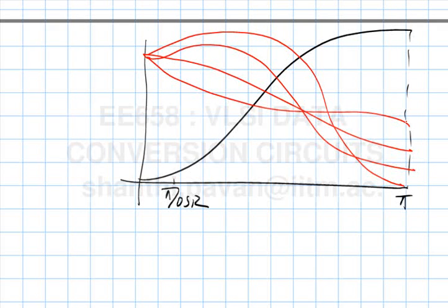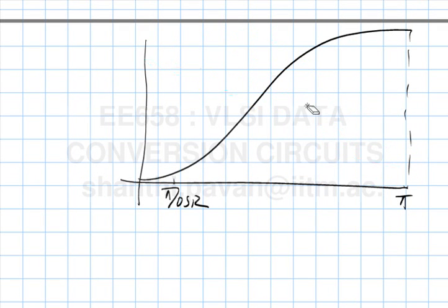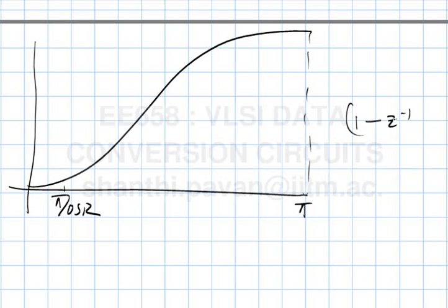And the answer is more a practical one. So what people do is recognize the fact that a lot of work has been done. People have really beaten to death IIR filter design. This is nothing but an IIR filter, right? So (1 minus z inverse) whole power 4 in this particular example, divided by D of z, D of z inverse is nothing but a high pass filter.